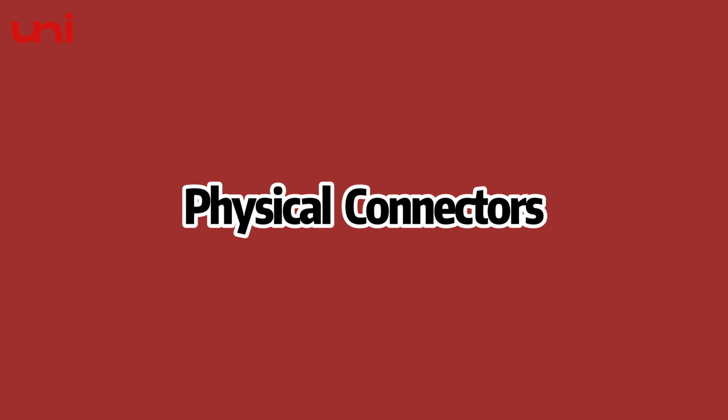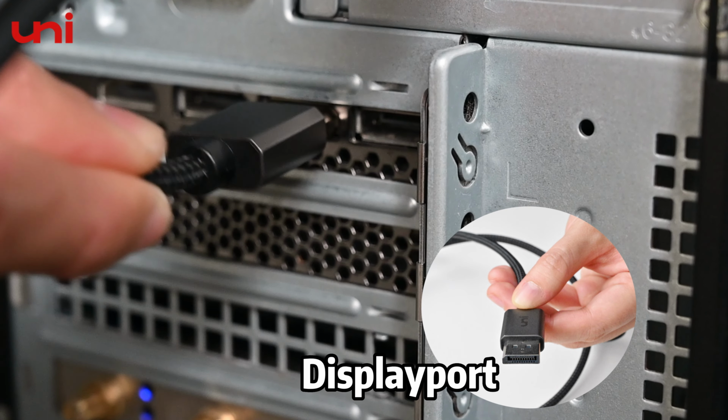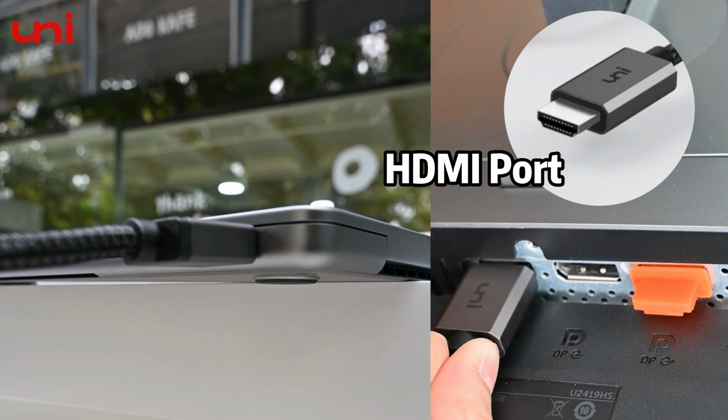Let's start by understanding physical connectors. The major difference between DisplayPort, DP, and HDMI cables is in their physical connector design and the type of devices they're meant to connect. DisplayPort has a smaller and more compact connector with 20 pins, while HDMI has a larger connector with 19 pins. DisplayPort has a rectangular shape with a trapezoidal slot at the top of the connector with an asymmetrical shape, while HDMI has a more rounded rectangular shape with several curved sides.